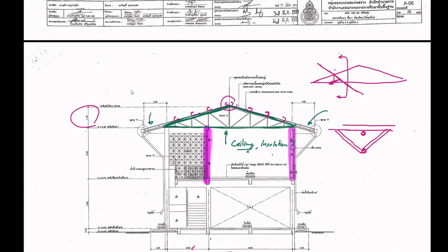Yes. You wouldn't want to sit in a room and see the truss, and it would be pretty hot. You can add the weight of the ceiling and insulation and so on to the roof right away. You don't add it on the bottom chord just to make your life more miserable.